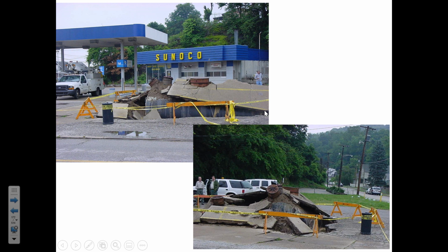But it's this rare case where, with really rainy weather, the water table went up, and this filling station no longer being used, the fuel tank was empty, so that it didn't have much weight. And so the buoyant forces exceeded the weight, the downward forces, and it caused essentially this tank to float, even though what we usually think of floating is in open water. It can also happen in saturated soils. So this is kind of an interesting fringe situation that illustrates that buoyant forces sometimes apply even in circumstances that you wouldn't expect.